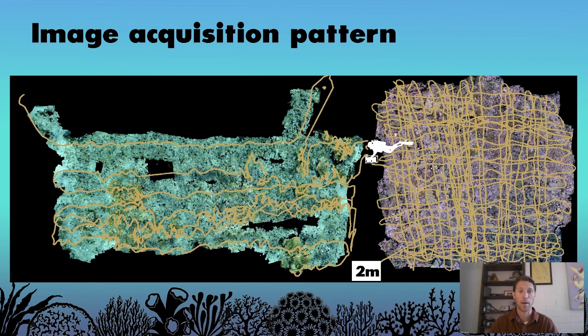First, let's focus on overlap. It is important to have a way to navigate around the plot to make sure that you have covered the entire area. This applies no matter the scale or the imaging platform that you are using. Again, the most important thing is overlap, so you need to make sure that you have a way to achieve it consistently. This requirement gets harder the bigger the plot area is. In a small plot, a diver might be able to navigate their way around the plot by memory, while in a larger plot, visual markers such as temporary floats are highly recommended. For AUV or towed surveys, GPS navigation will almost certainly be required to ensure that you're maintaining good coverage of the entirety of your plot.